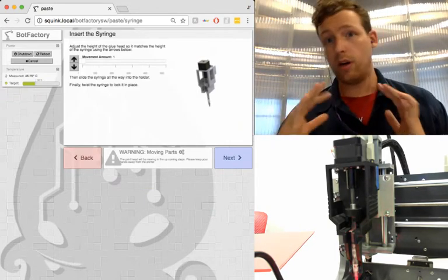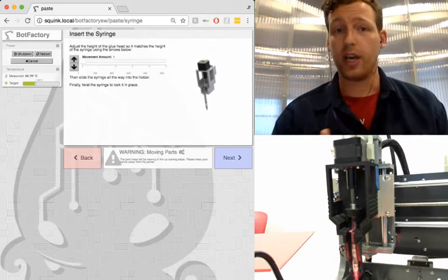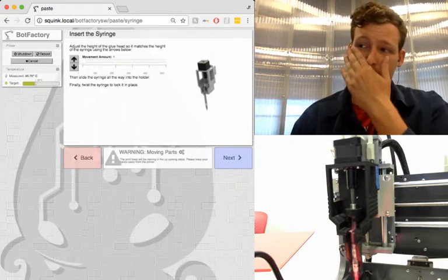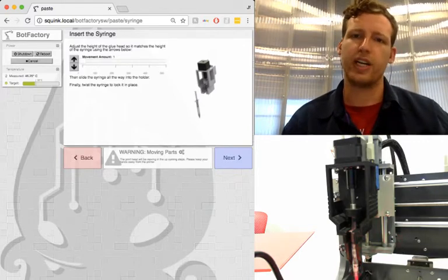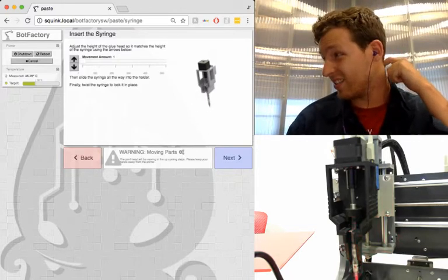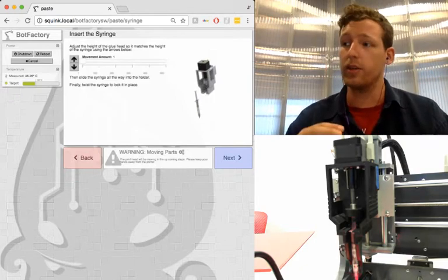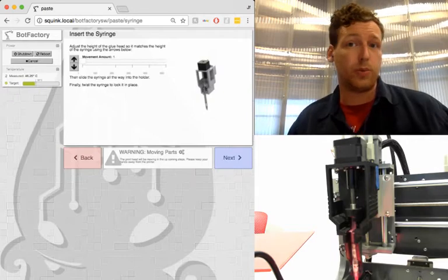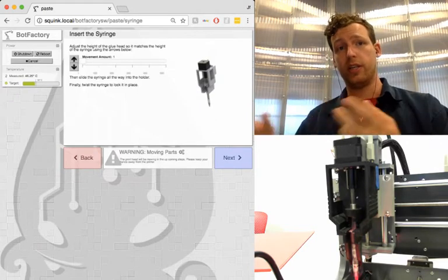You can use other materials you want, and we don't care. You can use one-part epoxies. We found that we just weren't able to heat it up fast enough, or at least heat it up to the temperature at which a one-part epoxy would cure properly. If you have a reflow oven, you can use one-part epoxy, and then after you're done, place it in there.